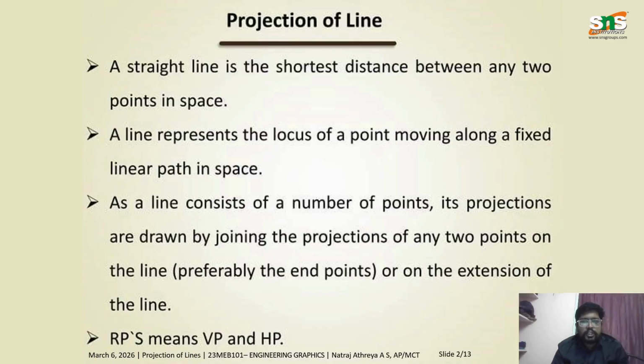Each point is projected, right? So when you project each point further, it leads to projection of lines. Thus, based on the projection of points, the projection of lines should be drawn, and it will be the extension of the line. To represent that, we will have the vertical plane and the horizontal plane. These are the reference planes.